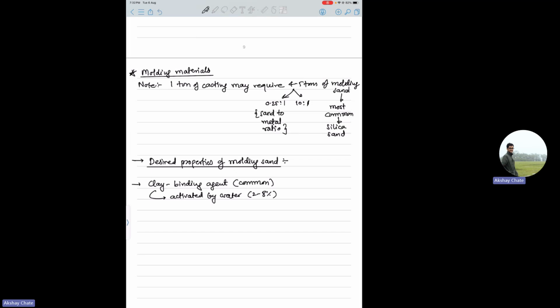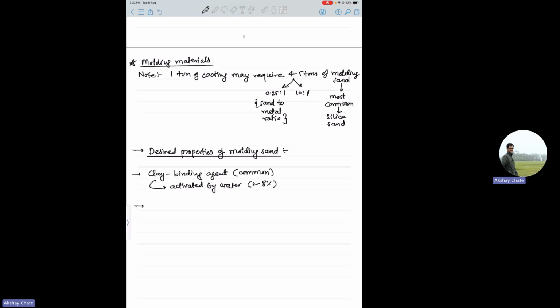One is the grain size test. Basically, you try to find the grain size distribution of your sand, and the finer it is, the higher the grain fineness number. That is another one-liner: finer sand leads to a higher grain fineness number, sometimes called GFN. Keep that in mind. There is a formula for that, but it's basically a weighted average of different particle sizes in your sand, and the weight is taken by some multiplier already given in the table. So you need not mark those things.